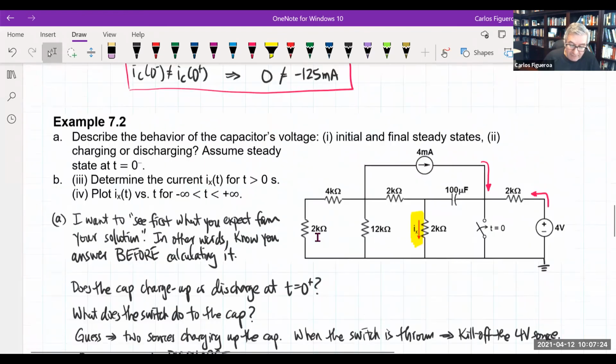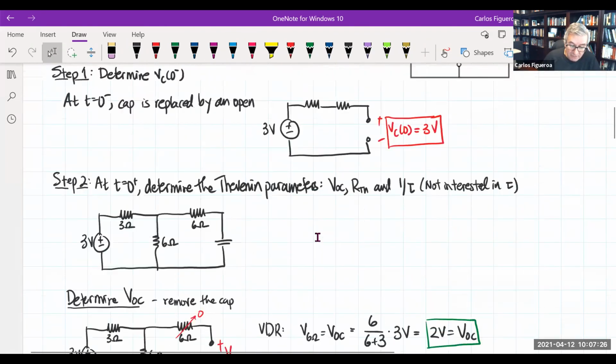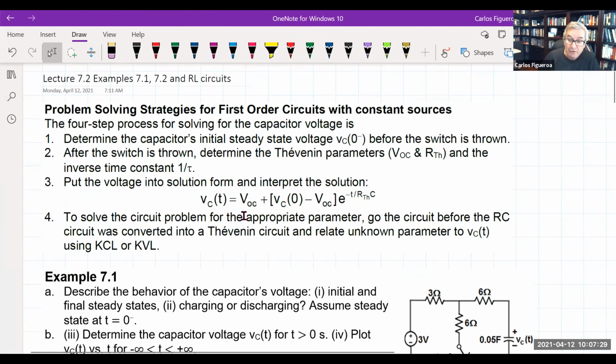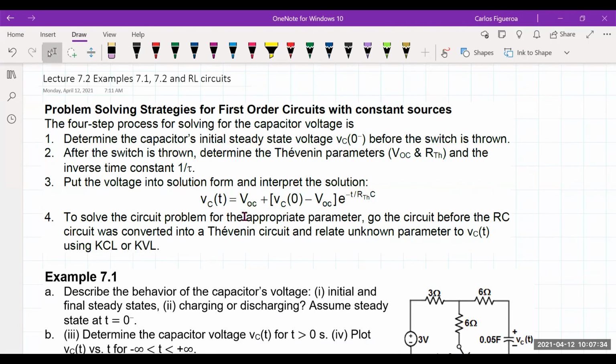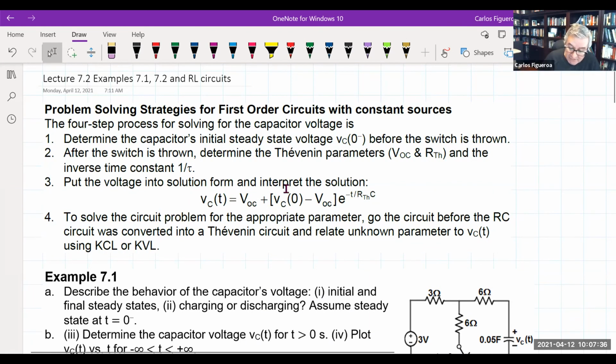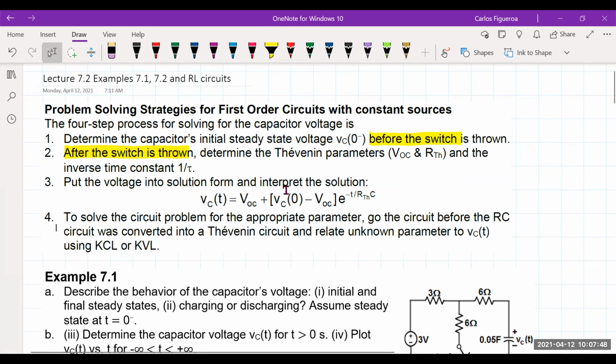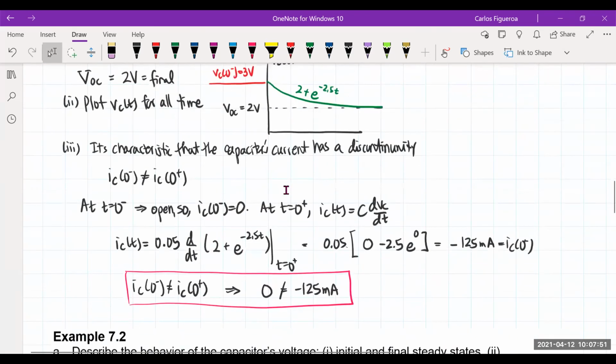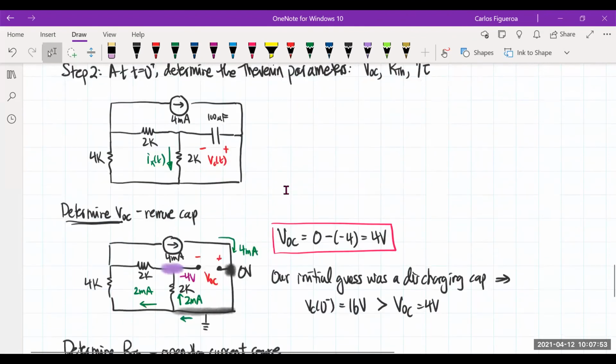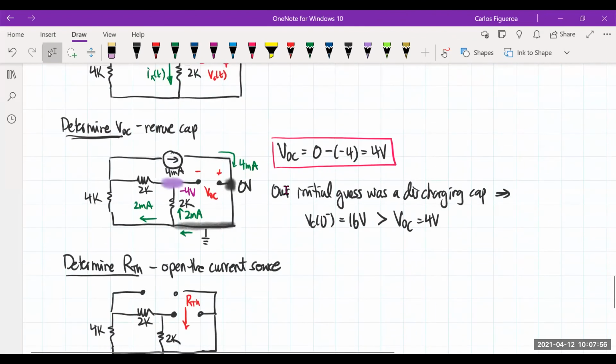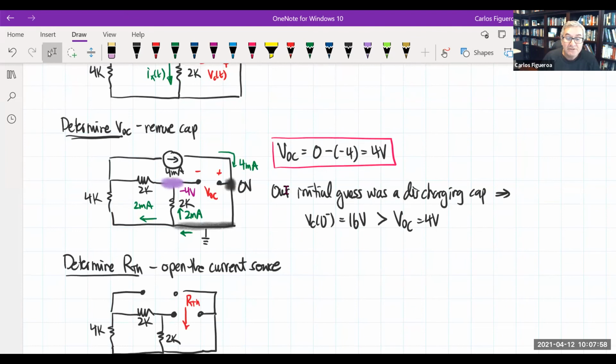I think we've already defined that when we go calculate voltages, we're using this relationship. VOC immediately implies 0 plus. It never implies 0 minus. That's why it says right here, this is before the switch, and then here it says after the switch. I think we defined that pretty clearly already. Okay, so your concern is not only is it redundant, but it's actually potentially confusing because VOC is always at 0 plus. I would just say go read what the strategies have been said.